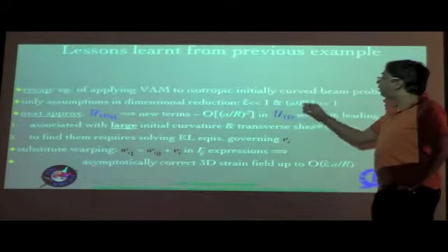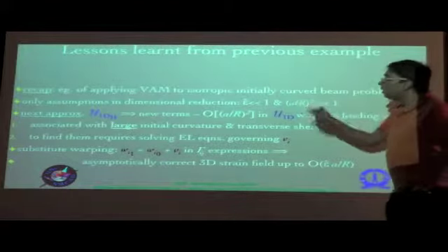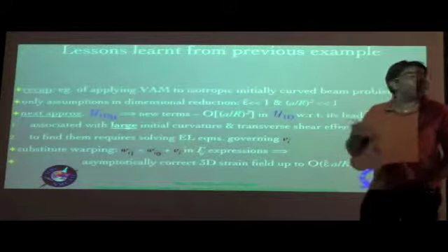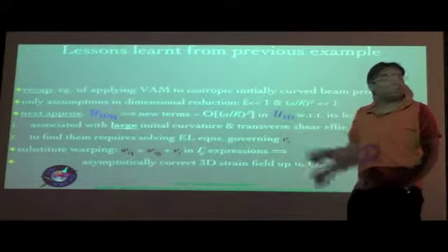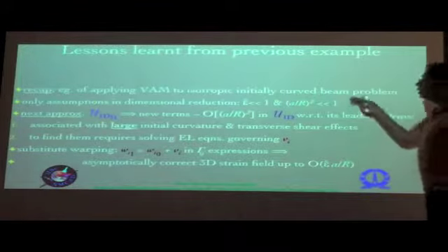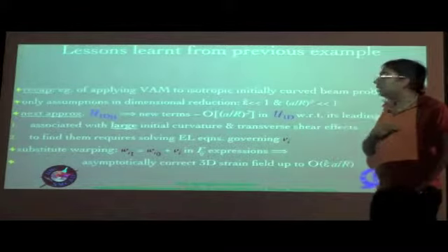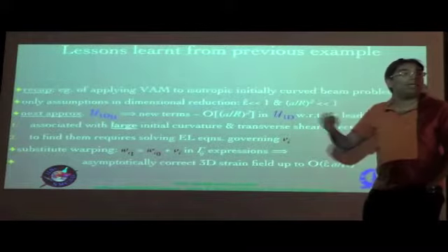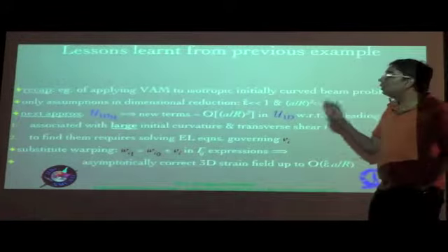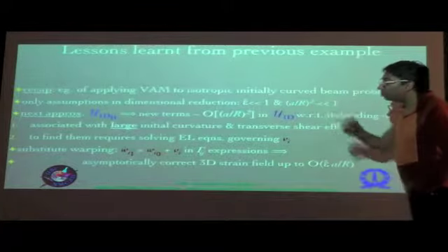So therefore we basically said that a by R squared is small compared to 1. Which means that a by R is typically of the order of 10%, whereas a by R whole squared is of similar order as epsilon hat, which is of the order of 1%, so 10 power minus 2. That is the kind of small parameters that we used, and that contains a very wide class of engineering problems in all branches of engineering, in particular in aerospace engineering, where this becomes applicable.